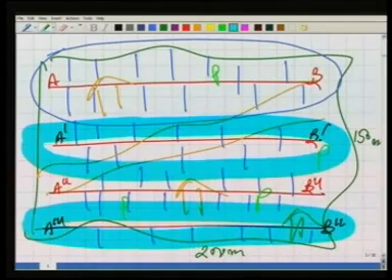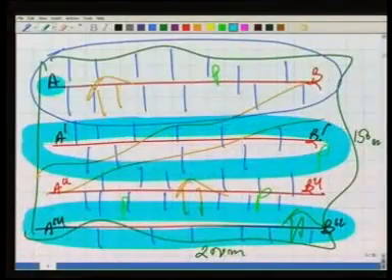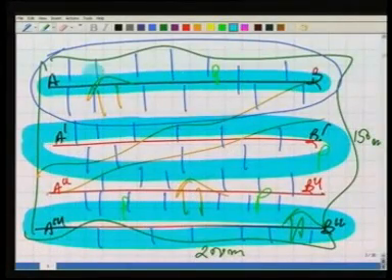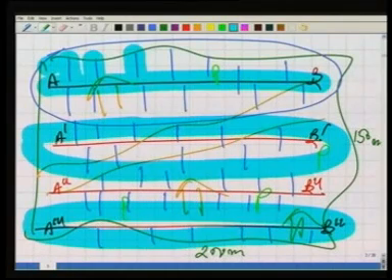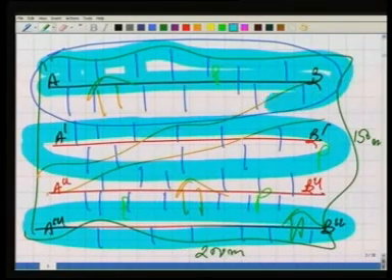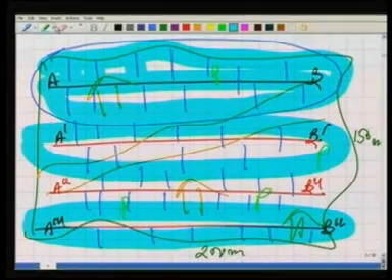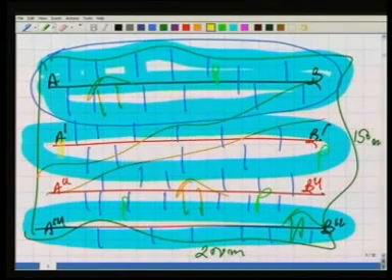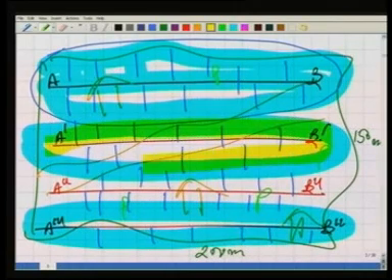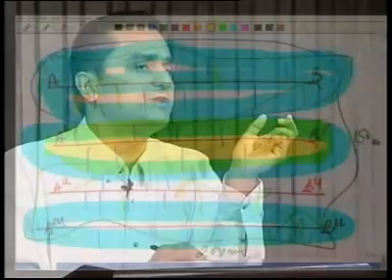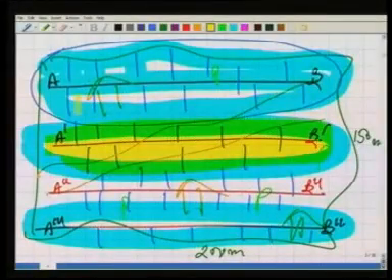Now, when you are going to plot it in the drawing sheet, you can plot, for example, this line AB as well as all these offsets. So this entire area can be plotted. Now, you can plot this area also, but there is a question now. When you are plotting this area and this area, the chain line AB and the chain line A dash B dash, how are you going to relate them?